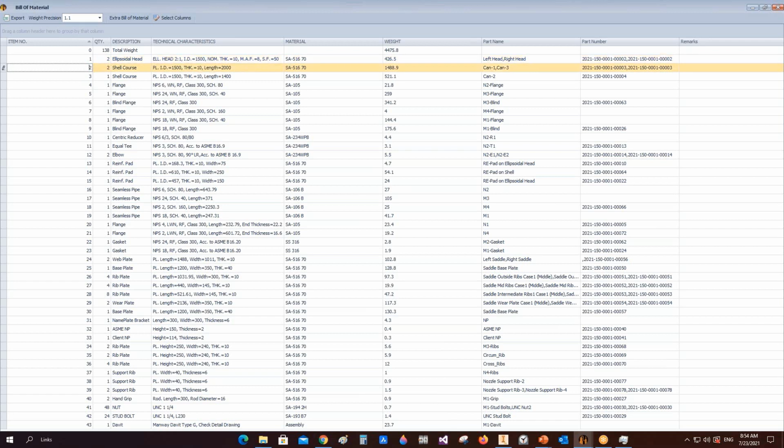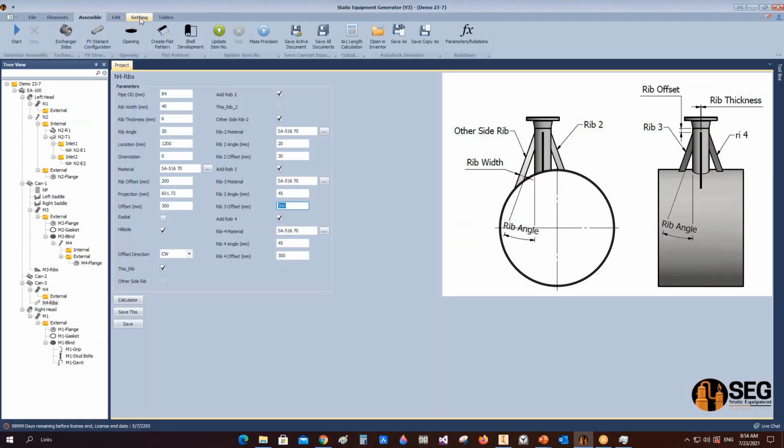So to update the item number to Autodesk Inventor, we need to make one more step before proceeding with the drawing by clicking on Update Item. This step takes around between 1 and 2 seconds for each element on Autodesk Inventor, so it depends on the number of elements in your project. It may take 30 seconds or 1 minute, maybe more if you have a larger project.